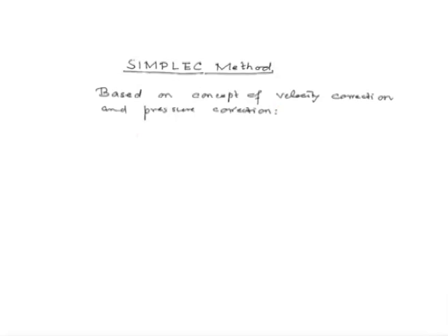That is to say, we would obtain the velocity field V_i^m as the sum of our intermediate velocity field V_i^m star. Now, this V_i^m star, remember, we had obtained using the linearized version of the momentum equation, wherein for the right hand side evaluations we have used values of the velocity field and pressure field at the previous iteration.